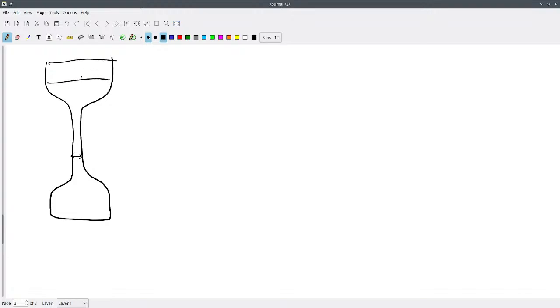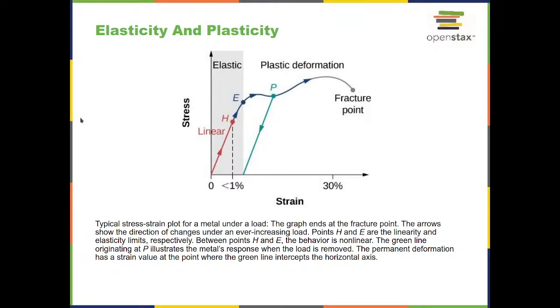We clamp them between large hydraulic presses or tension machines, apply a force on either side, and we measure the change in length of this object until, of course, at some point we reach that plastic deformation and then ultimately the fracture point, and then the piece breaks in half. And so we use that kind of technique for characterizing materials, characterizing their elastic region, their elasticity, their Young's modulus, and then when they reach the plastic deformation point and the fracture point.